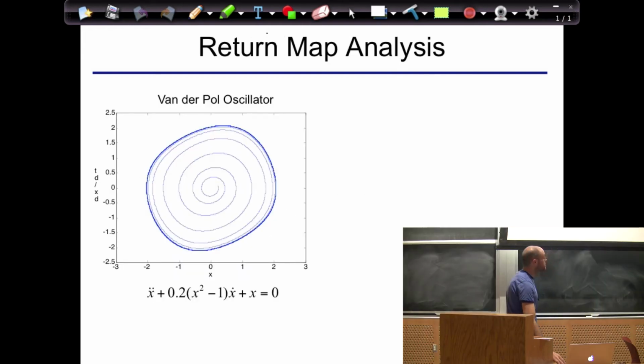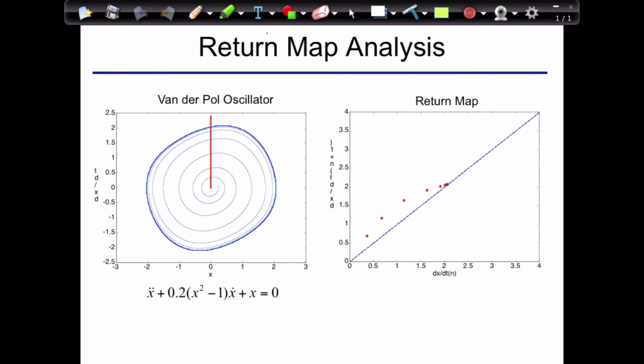Okay, so you recognize return map analysis. I picked a surface of section. You can plot the return map, okay? So I said for the walking robot, we should do something like a return map based cost function, right? So the observation was the optimal return map would be the deadbeat controller, would be a flat line.